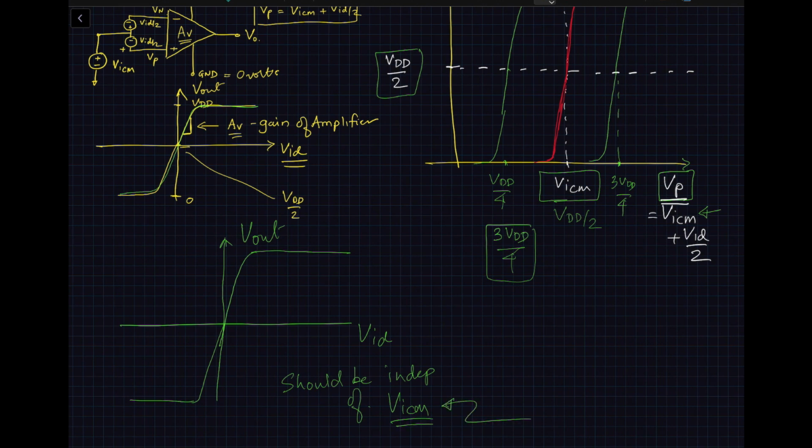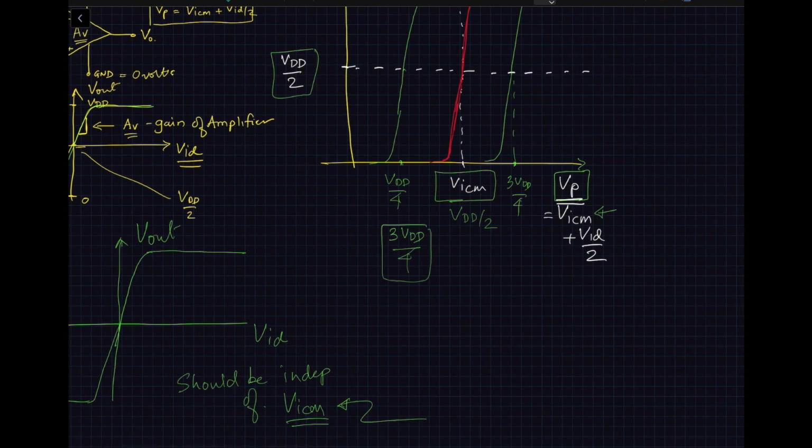And this Vicm is the one that I explained to you a while ago. That's like a common mode signal, which is there on both sides when you're doing this ECG example. What we are trying to identify is not to amplify the common mode signal, but the difference between the two. So, to give you a little visual imagination of how this signal is going to look, let's say this is our 50 hertz, something like this.